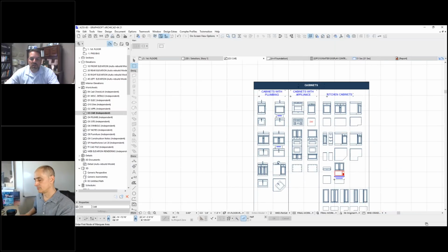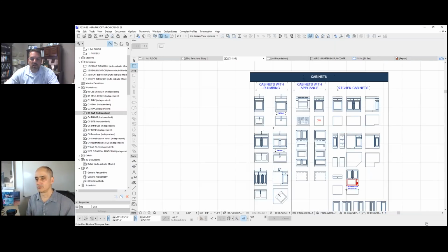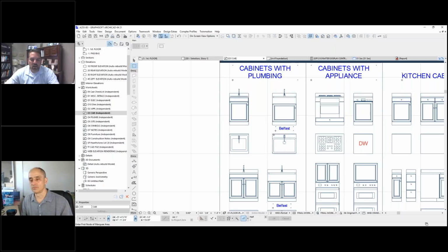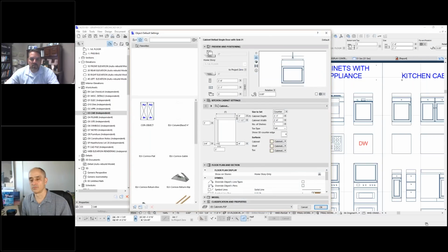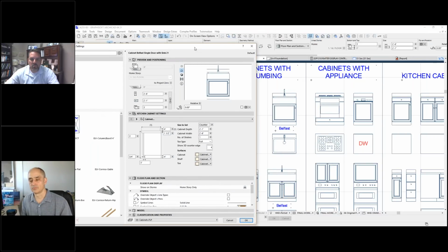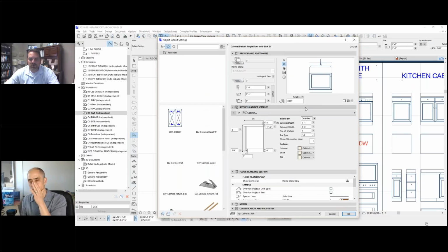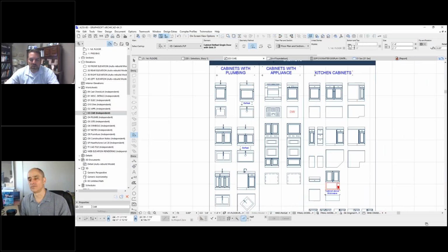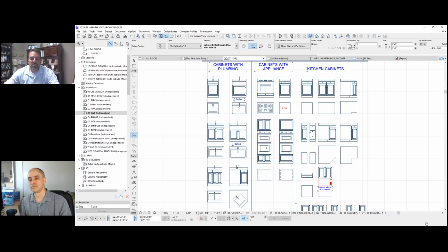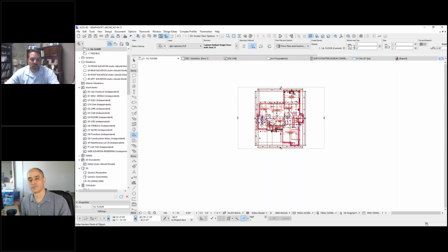So now when somebody's working on a project, they can easily see, by alt-clicking to get those properties, that object is set to the same parameters. So it's almost like a visual favorites, except by having them all, you can view them all quickly. It just makes a fast way to select, and also by showing this as a trace reference, you can be on your floor plan and show it as a trace reference.